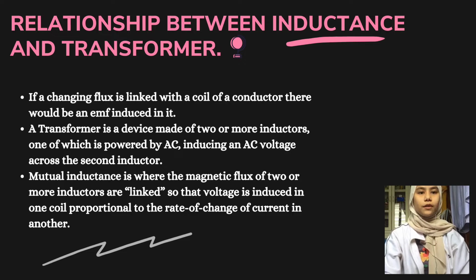A transformer is a device made of two or more inductors, one of which is powered by AC, inducing an AC voltage across the second inductor. Mutual inductance is where the magnetic flux of two or more inductors are linked so that the voltage induced in one coil is proportional to the rate of change of current in another.